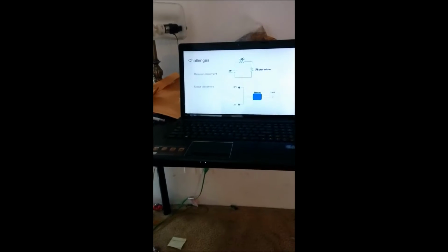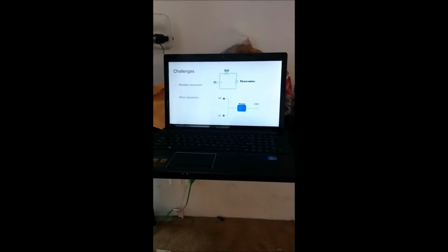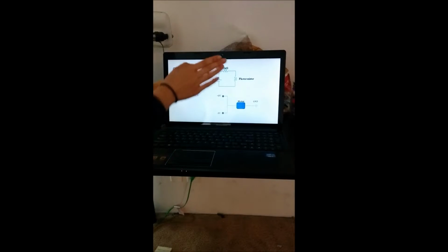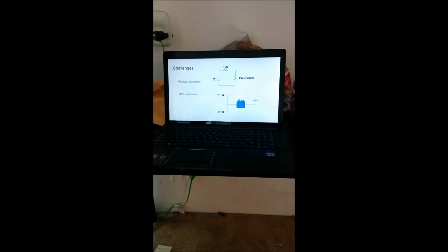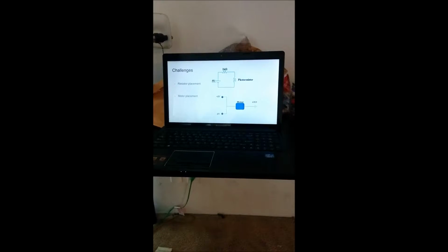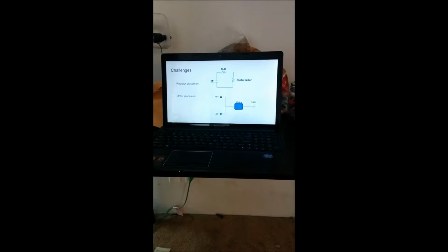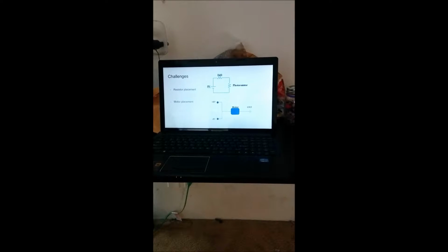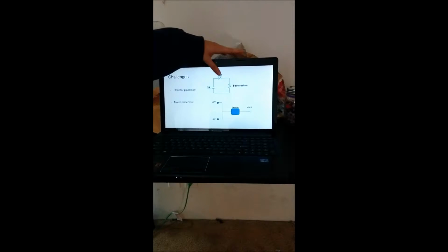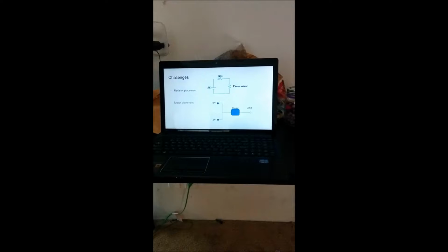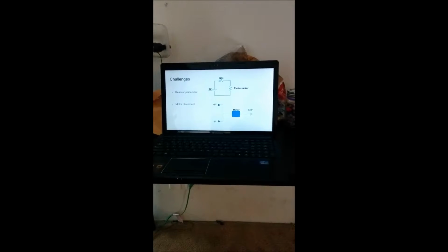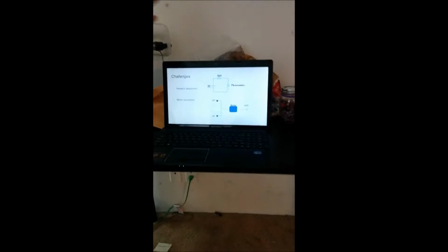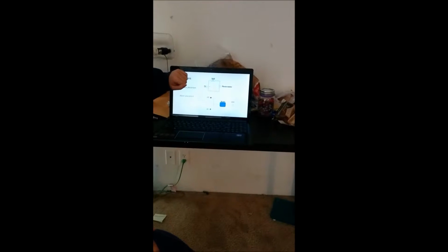So some challenges we came upon when trying to build these circuits include resistor placement. As shown here in the first diagram, initially we did not include this resistor here. We only had the photoresistor. We were trying to find the voltage drop across it to see why our circuit wasn't working. And we realized that by only having a photoresistor within a circuit, if you shorted this resistor here, it was irrelevant what resistance we induced upon the photoresistor by manipulating exposure to light, because all voltage had to drop across that one circuit component.